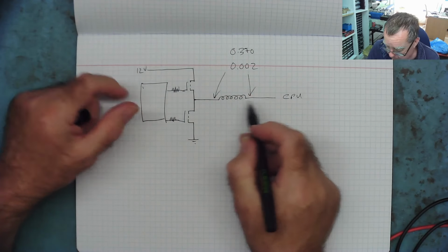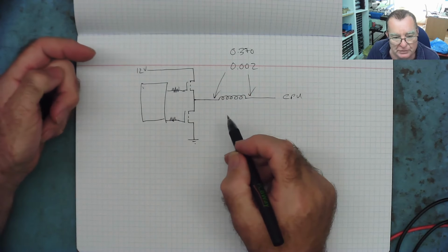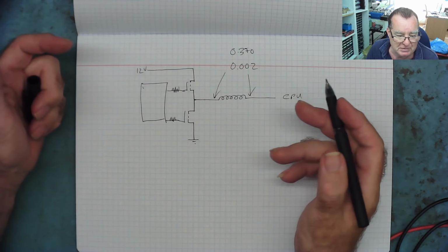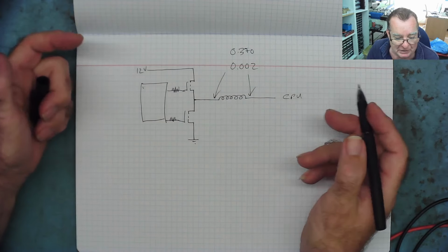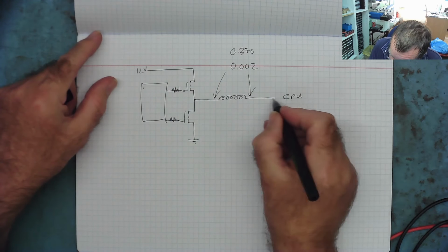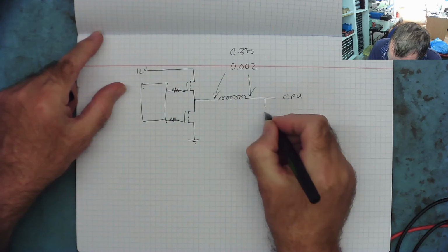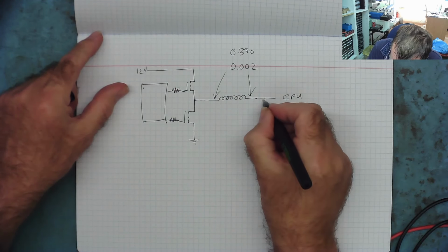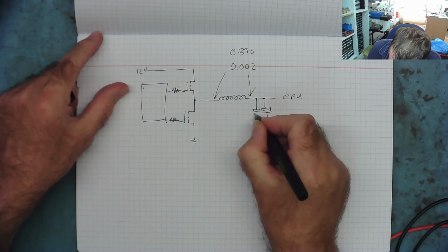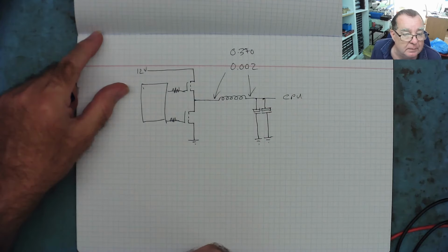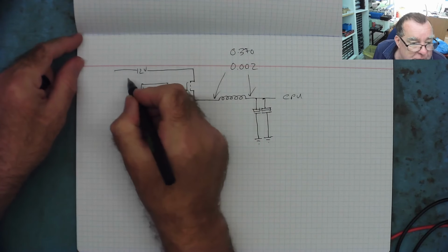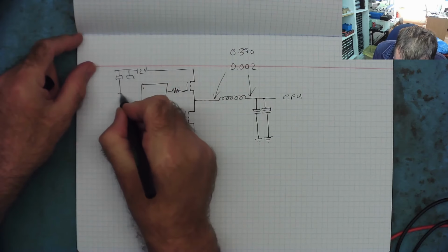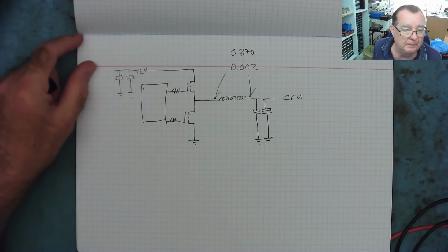We know that inductors appear as a resistance to the ESR meter, yeah? We've just looked at that. We know that capacitors appear like shorts or very low resistances, low ESR, to the inductance meter. Okay, your CPU on here will have lots and lots of capacitors going to ground. Yeah, lots of them. Many, many, many. Electrolytics and other little capacitors going to ground, yeah? Okay. The 12 volts will have, wait for it, lots of capacitors going to ground. Yeah?